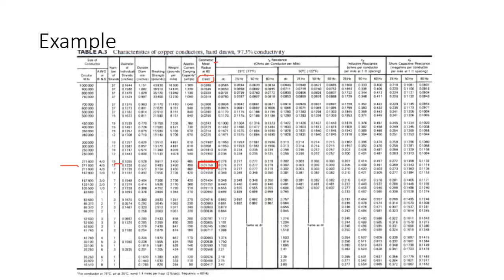But if you're talking about this 50 hertz here, this is a different story. This is for the resistance. So if you're asked, for example, to find the resistance, you need to understand how to find the data from here. Therefore you will use this 50. But because we talk about the inductance, it's not given in 50 hertz, it's given here as 60, the geometric mean radius.